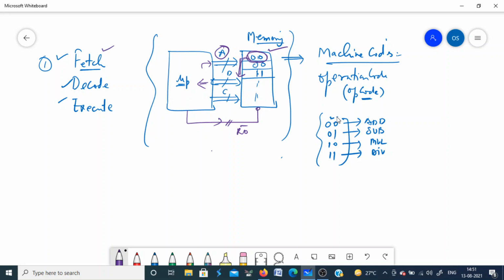So this part is okay. You have taken the data from the memory inside the processor in the first part. In the next part, the processor will decode this data. This is a very important thing. There is a separate decoder inside the processor, called the instruction decoder. You have binary data coming inside the processor, and the processor has to understand the meaning of this binary pattern, because based on that it will go to the third step, execution. Decoding means understanding the instruction, that is, what operation is to be done by this microprocessor.